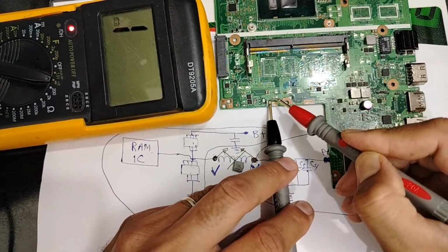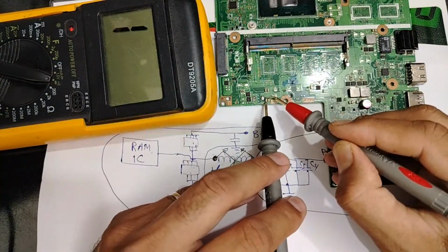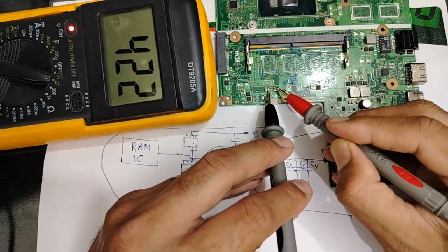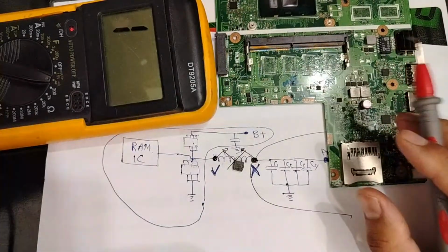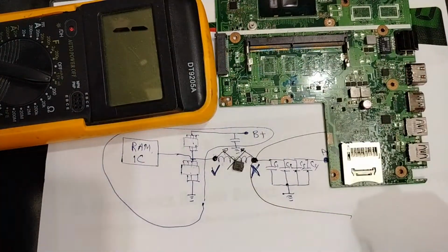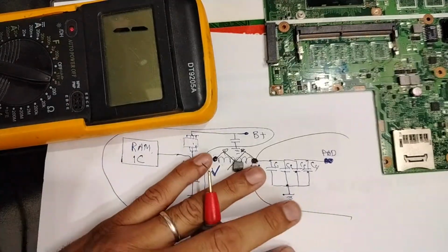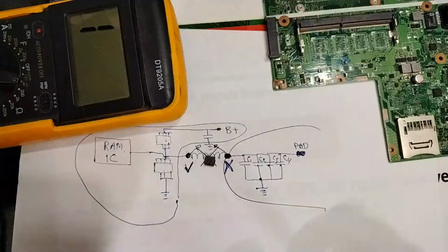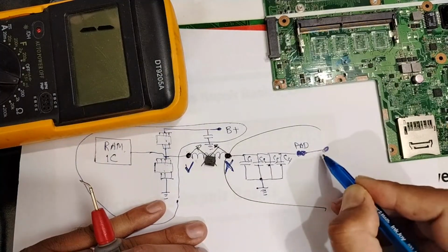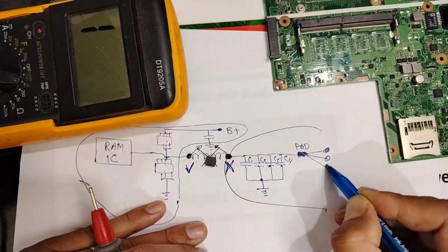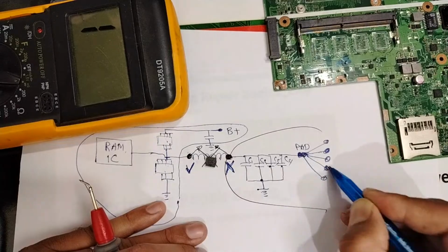For beginners, of course. You see? Zero shorted. This one. Shorted, shorted, shorted. Okay, nice. Now, the deep work. Please pay attention. We find that the problem is here. But the problem, my friend, is that we have this pad here and this pad connected to 5 points. Means 5 small circuits. 1, 2, 3, 4, 5.